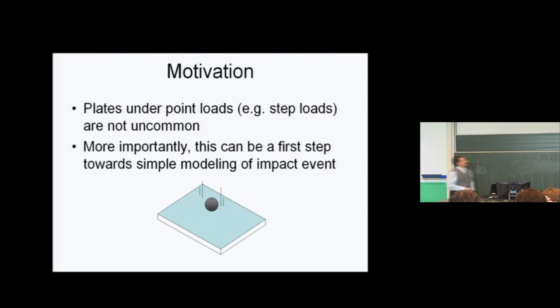Is because, first of all, walking loads, step loads, especially if you have high heels, which is quite concentrating the load, are essentially a floor with a point load. More importantly, impact. Impact is, of course, a dynamic problem. We'll talk about that in the next quarter much more. But as a first cut, especially for a series of impact problems called low-speed impact situations, you can start the solution by trying to solve this problem of a point force acting on an anisotropic plate.